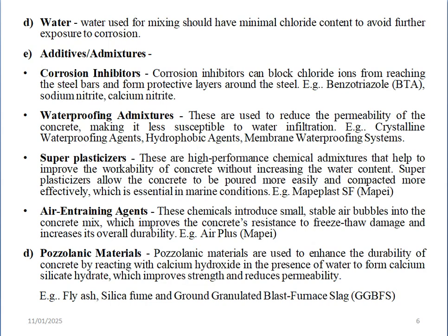Pozzolanic materials. Pozzolanic materials are used to enhance the durability of concrete by reacting with calcium hydroxide in the presence of water to form calcium silicate hydrate, which improves strength and reduces permeability. For example, fly ash, silica fume, and ground granulated blast furnace slag.